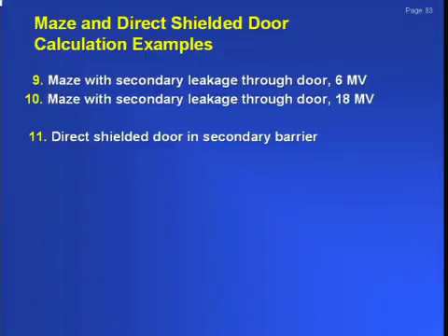It's disappointing that NCRP 151 and McGinley's book don't look at the double-legged maze, so they're not doing door calculations for a double-leg maze. I have done several double-legged mazes. They're basically just another segment of that calculation. You use the same methodology, but I can go through with you on our assumptions for a double-legged maze. If you really want to, give me a call, and I can tell you what we use. The double-legged mazes work well. I know exactly what you're talking about. It saves you tremendously on your door. I mean, we have doors that really don't require anything if you use a good double-legged maze.